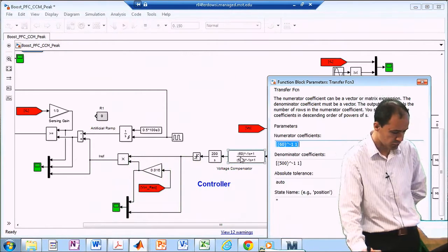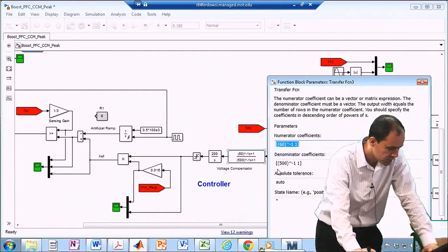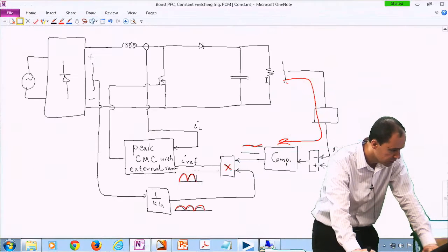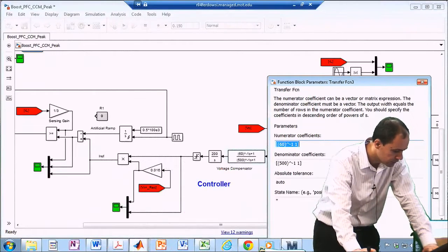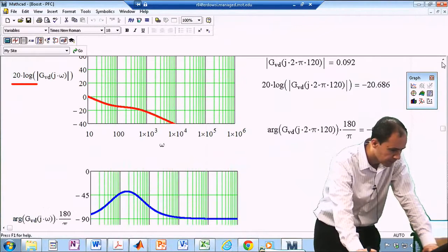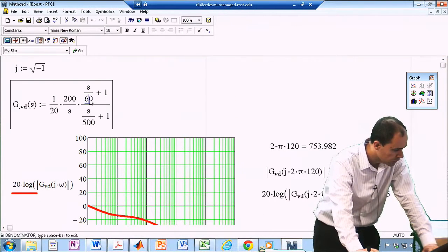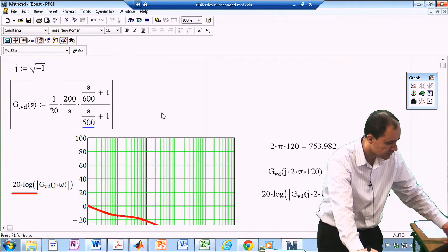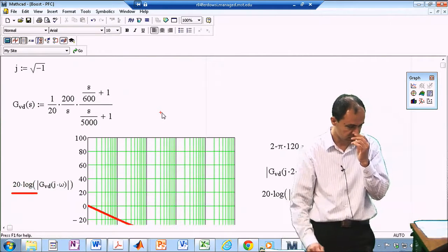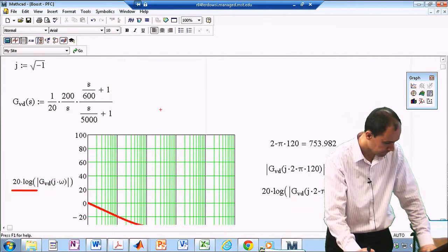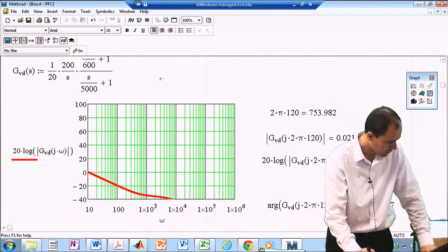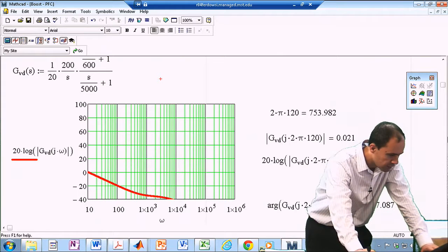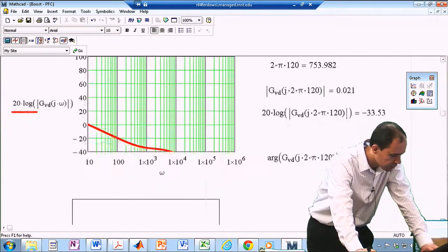this controller so you guys can see what happens. For instance, I am going to move. Okay, hold on. Let me do it theoretically first. So what if you come out and say, okay, instead of 60 radians per second, I use 6,000, and instead of 500, I use 5,000. You still get a good attenuation over here, but then your phase may get a little bit disturbed.